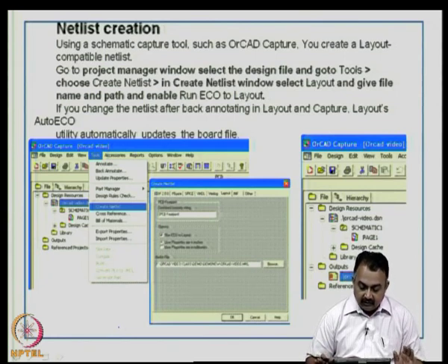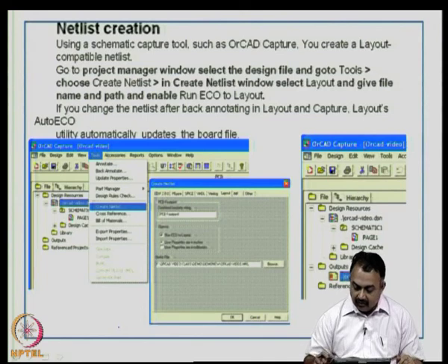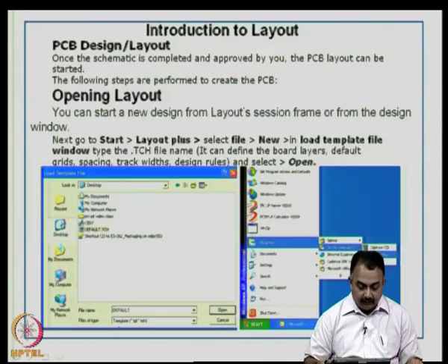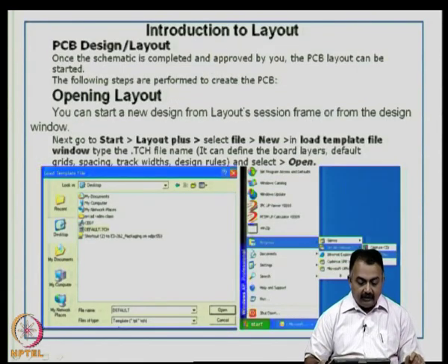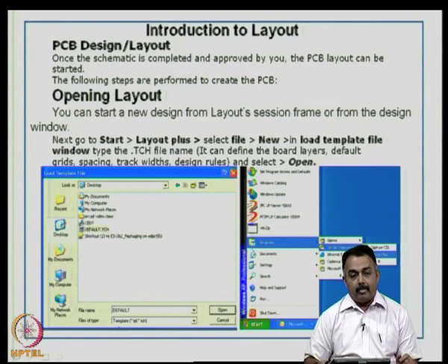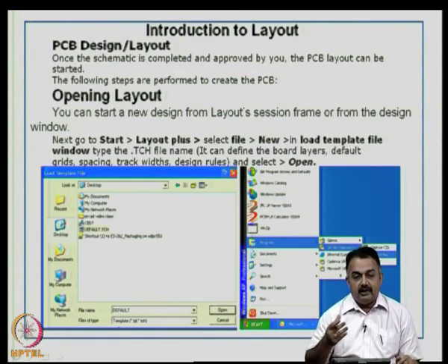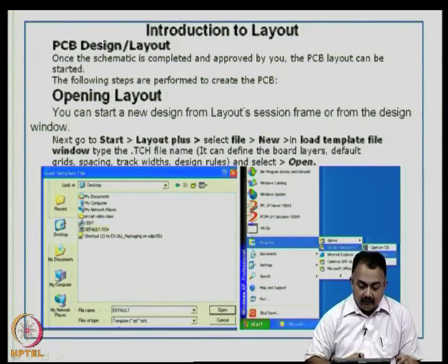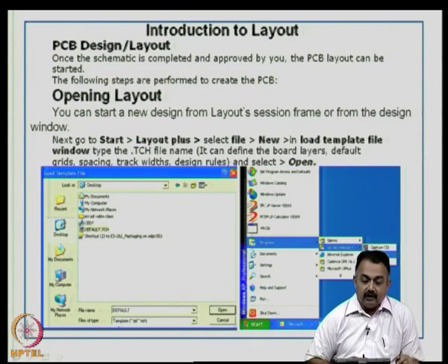So, create a netlist basically using the nets that you have generated by placing the wires. So, accordingly you can create your own file name which needs to be inputted later. So, finally, the netlist is ready. The netlist, as I said, is a very essential tool for understanding your electrical work.